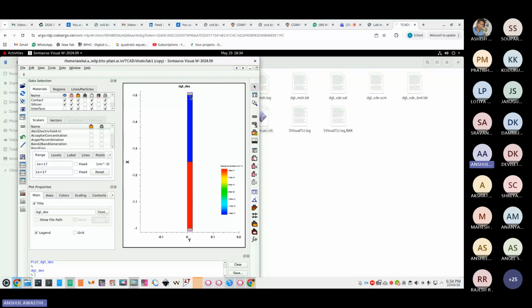So to see inside the device, I want to cut it exactly into half with respect to the x-axis, to see the device physics. So I have to create a cut that divides my device with respect to the x-axis into two halves. If you can see this y-axis, it is exactly at the center. If my device size is 20 nanometers, it will be exactly at the center.